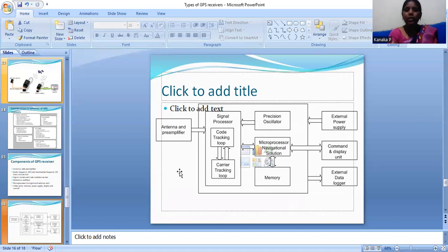With this device, one can determine angles and distance from the instrument to the points of the survey, which is an application of trigonometrical angles. Distance may be used to compute the actual position of the surveyed points in absolute terms. So this is the basic principle of the total station. The total station gives very accurate measurements in surveying.